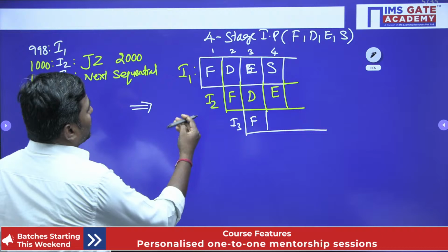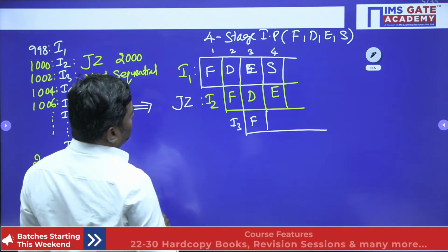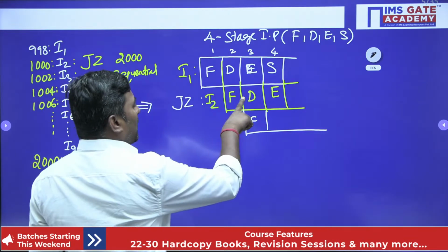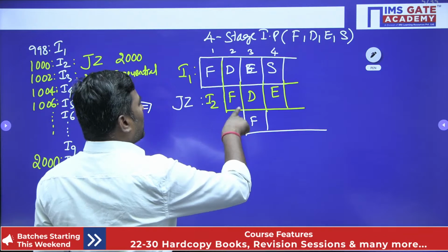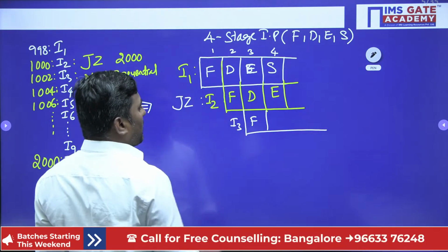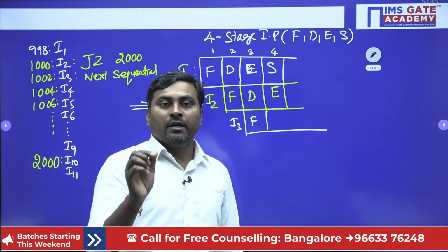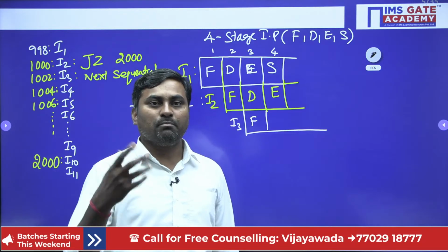So what is I2? I2 is a branch instruction, jump 0. Whenever I2 fetching is over, automatically PC is pointed to I3. When you are decoding instruction I2, you are fetching I3. Please understand here: if this condition is true, we are supposed to fetch which instruction? Let's take branch Z0.